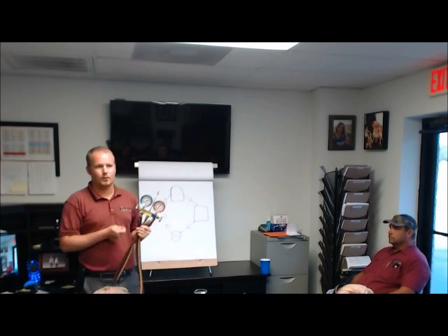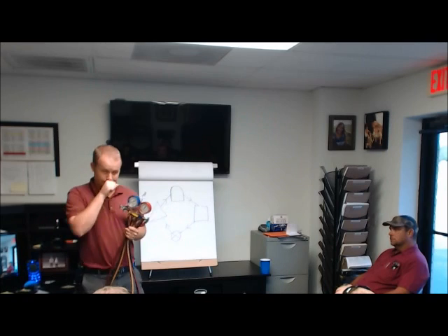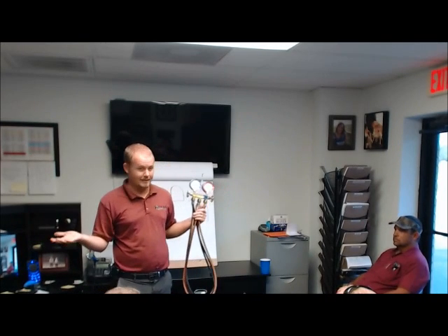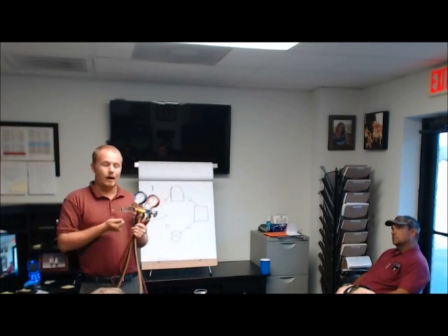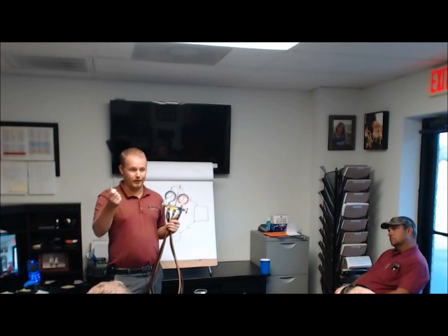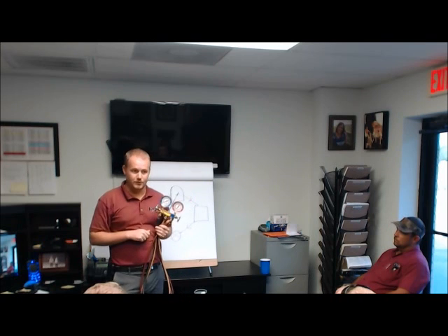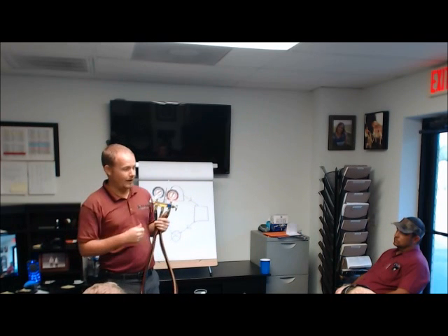When you take that static pressure, assuming that there is a mixture of liquid and vapor in that system, which there should be unless it's almost completely flat, you can then take a temperature around that system. So take it in the condenser, generally speaking, that's where most of the refrigerant is held. Take a temperature around there, and then